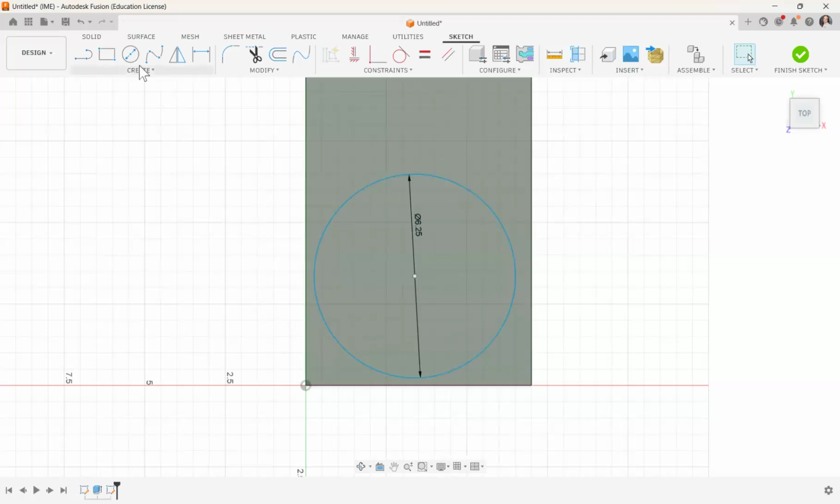So how we do that is we're going to create another circle, and we're going to select the center point of the same circle, make sure it's the same, and then we're going to expand it out. And how big should this diameter be? It should be 6.5, okay? So that leaves a 1/4 inch of space between the diameter of your coaster and where you want the machine to cut it out. Okay, so are we finished?